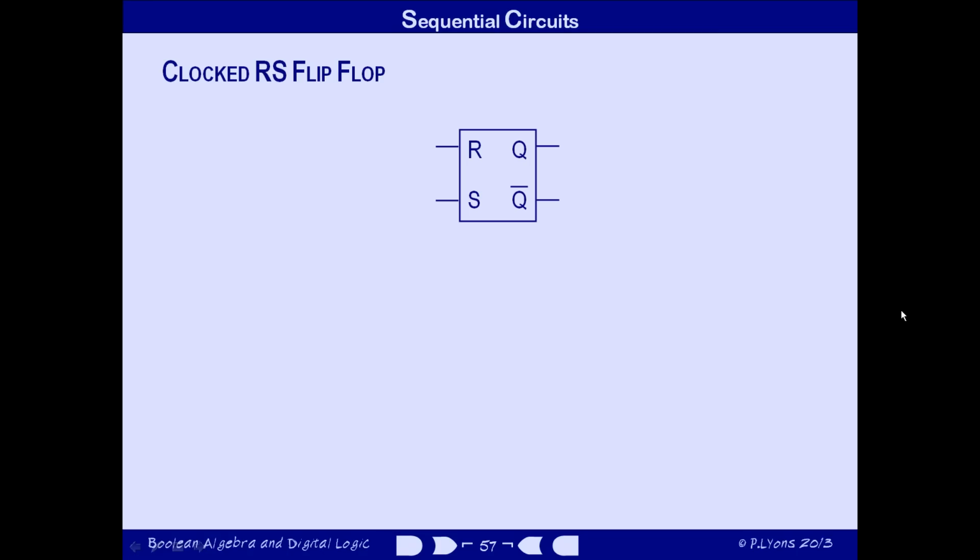You ought to make sure that a calculating component has enough time to complete a calculation before the output is used. So the clock input to a flip-flop isn't used to tell the flip-flop that it's 10 to 7, or even that 10 microseconds have elapsed since some prior event, but simply to make the flip-flop load some data right now. That's a pretty abstract interpretation to put on the word clock.